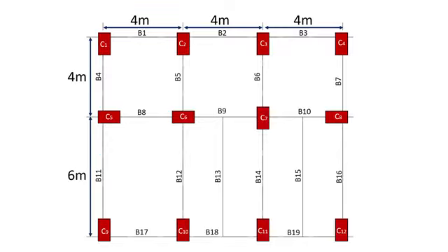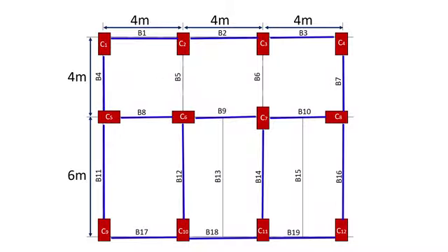It should be noted that primary beams are connected by columns at both the ends and secondary beams are those beams which are connected by walls or primary beams at least at one end. As you can visualize from this picture, only beam 13 and beam 15 are secondary beams, rest are primary beams.